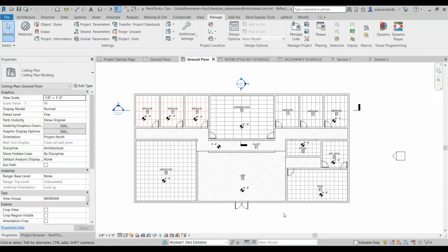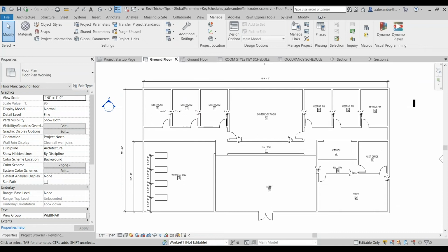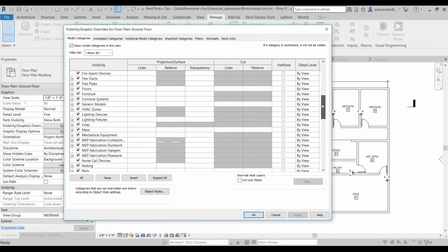And this is done by creating a custom key parameter for that Revit category, and then linking the category's elements to that particular set of data, right? And we'll see what that looks like. Now, the most prevalent useful application for key schedules is to define room information, so all the data associated with the room object. So here you can see, I'm just going to turn on my room.